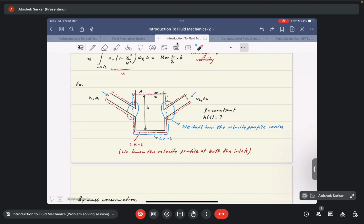That is, the volume of our chosen control volume changes with respect to time. So even if the density is constant, since the volume of the control volume itself changes, the first term, the time derivative part, will have a non-zero value, and we will obviously also have the net volume flow rate or mass flux terms.